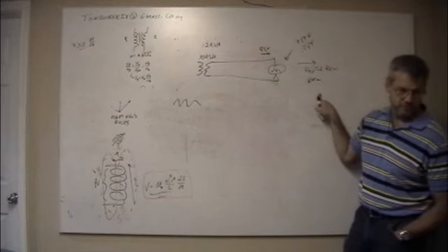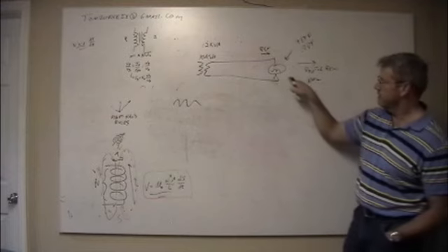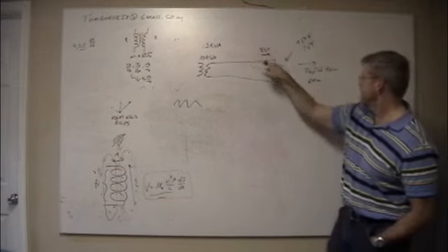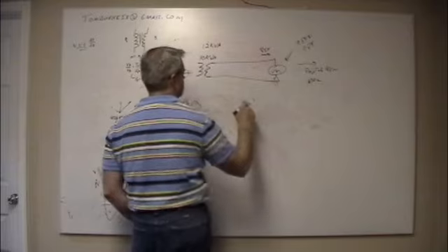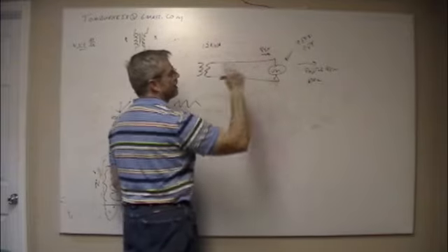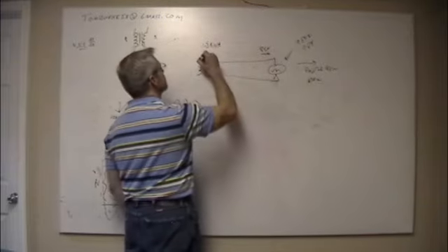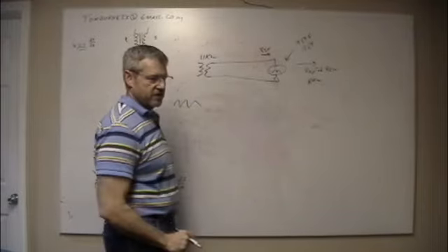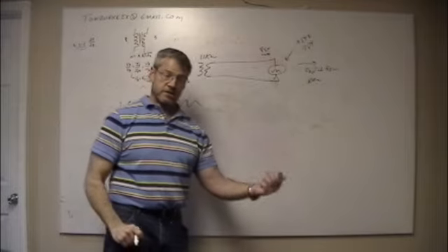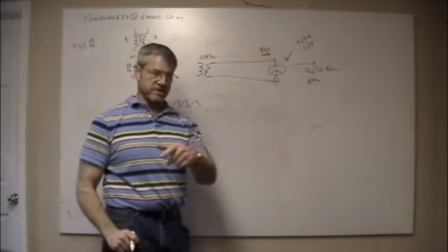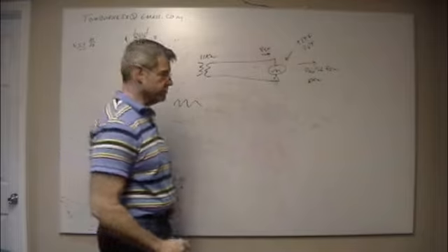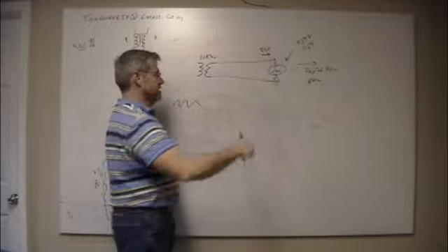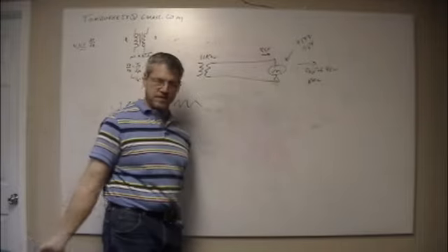So if I'm wanting to run that many horsepower over here, I come into this, I do a 0.9 efficiency, so now I'm already at, divide by 0.9, so that's like 11 kilowatts. So, you know, the beginner rookie thinks, well, I need an 11 kilowatt transformer. kVA, V times A, P equals IV, watts is equal to amps times volts. If it was a purely resistive load, 11 kilowatts and 11 kVA are the same thing.